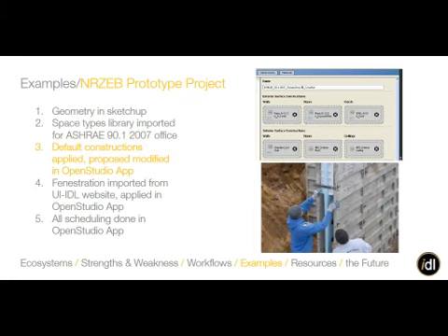But we did have to change some of the envelope. We did a thermal mass system, which was a concrete sandwich. So we had to define that in OpenStudio, which we did, and then apply that on the proposed run. So we were able to model this system with all its thermal mass capabilities and put that into the model, all within the OpenStudio application.